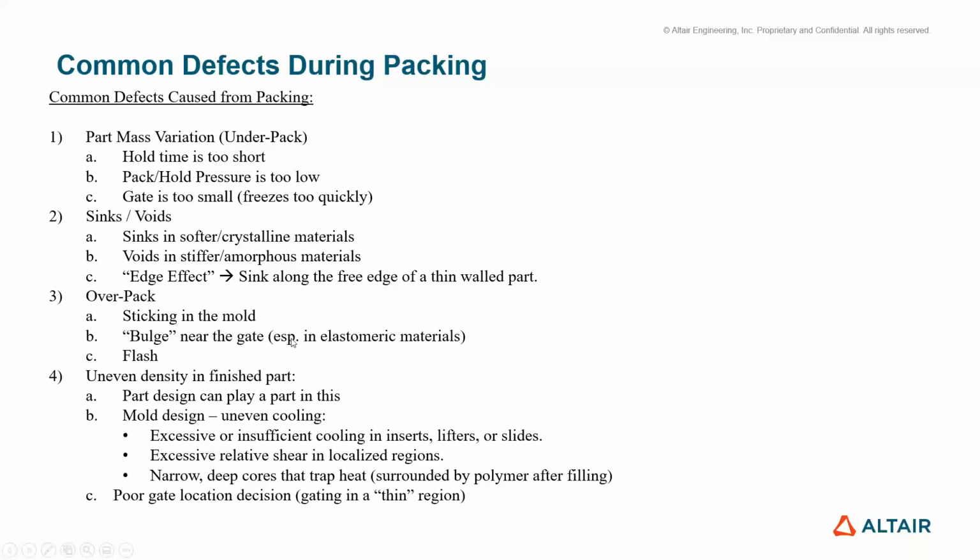Overpack. Sometimes sticking in the mold is due to overpack. If you pack these elastomeric, highly compressible materials too tightly, you might have trouble getting them out. Like your ejector pins just go right through the parts, even though you froze the part, but you stuck them because you might need to polish the ribs, or you need to not pack it quite so high.